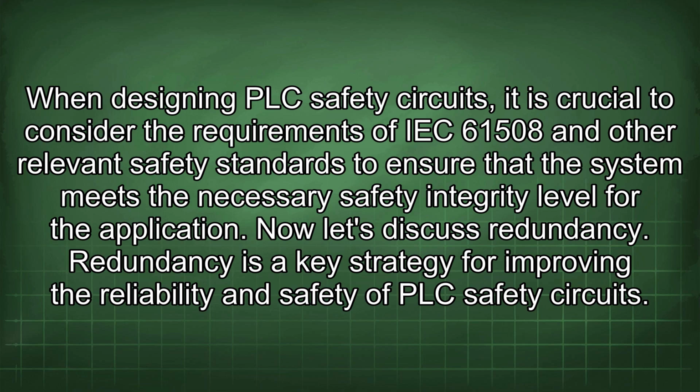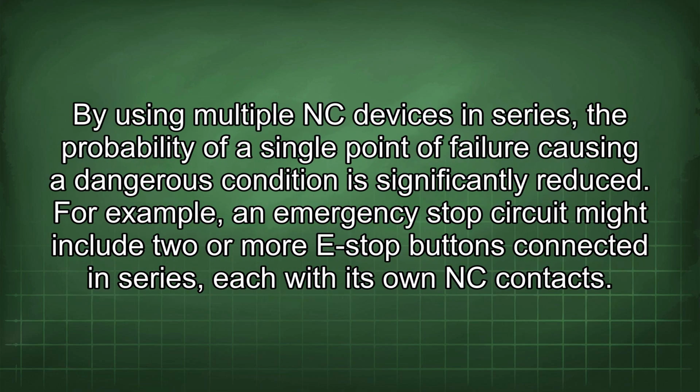When designing PLC safety circuits, it is crucial to consider the requirements of IEC 61508 and other relevant safety standards to ensure that the system meets the necessary safety integrity level for the application. Now let's discuss redundancy. Redundancy is a key strategy for improving the reliability and safety of PLC safety circuits. By using multiple NC devices in series, the probability of a single point of failure causing a dangerous condition is significantly reduced.